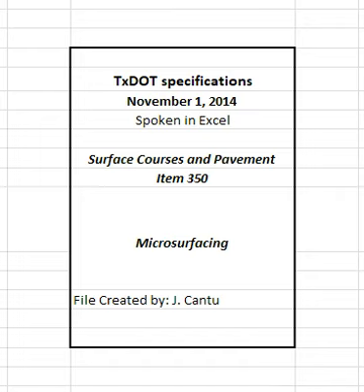3.2 Scales. Scales used for weighing aggregates and emulsion must meet all requirements of Item 520, Weighing and Measuring Equipment. The weighing equipment for aggregates may be either a suspended hopper or a belt scale. 3.3 Asphalt storage and handling equipment. Furnish a thermometer in each tank to indicate the asphalt temperature when continuous storage tanks are used. Keep equipment clean and free of leaks. Keep asphalt materials free from contamination.